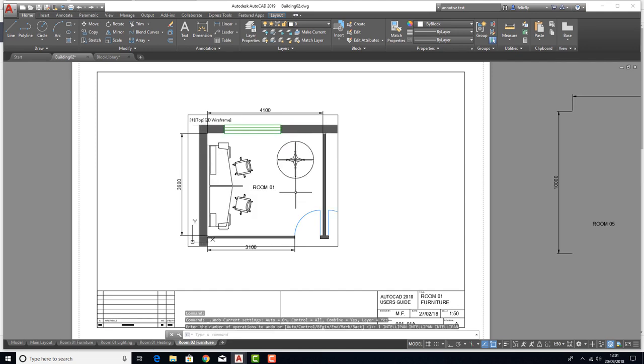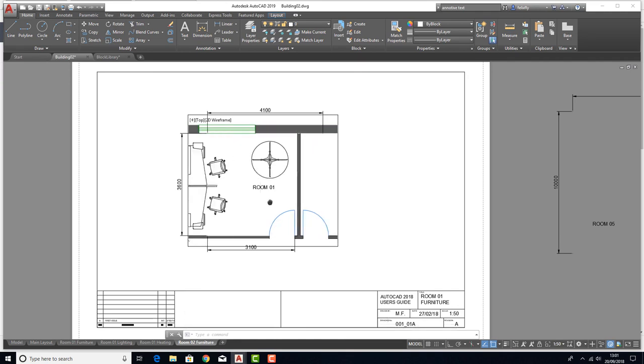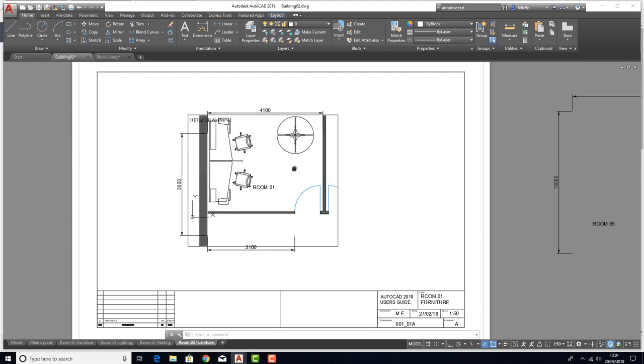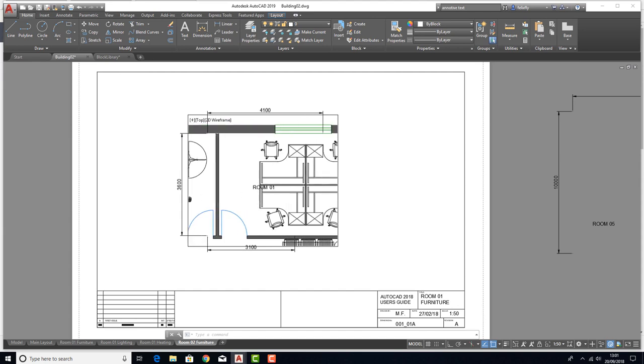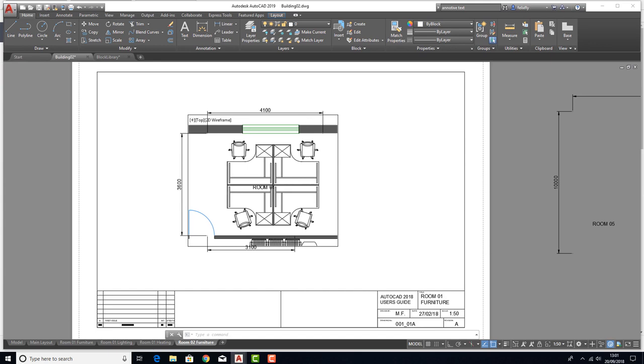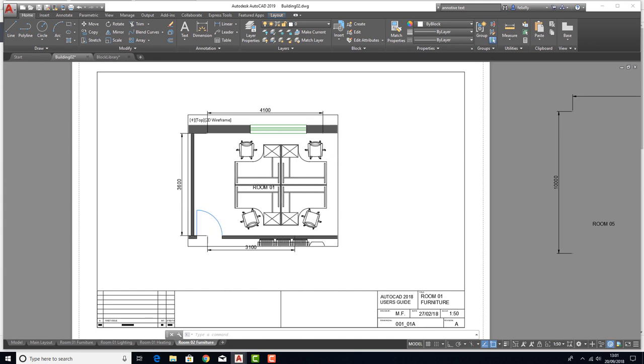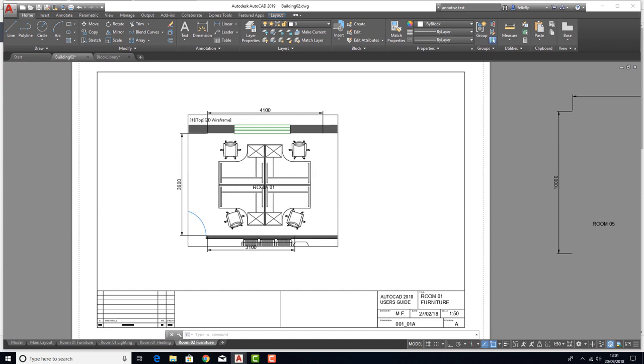So if I hold down my middle mouse button, before moving anything, I hold down shift, now it locks us, it turns on, it's like ortho. We can only go horizontally, you see. So I'm going to move it there, and I'm going to click outside.